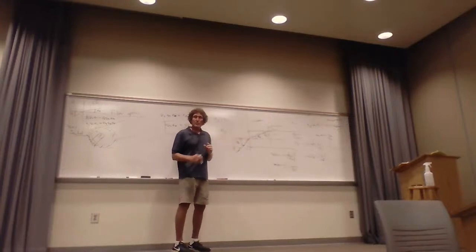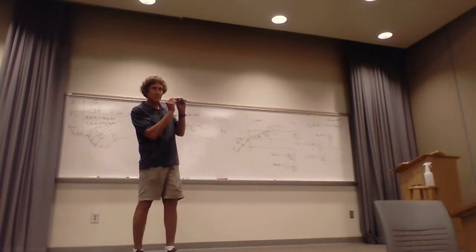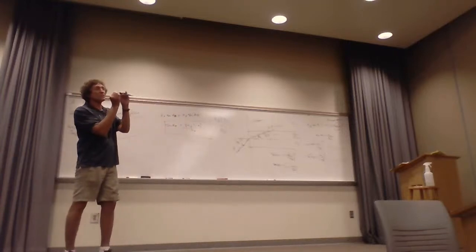But this is important because when you're dealing with fiber optic stuff, alignment becomes a problem. So you got a fiber optic guide here, right? And I'm going to feed it with a laser. Well, if this laser is not aligned perfectly, suppose the critical angle theta A is like 1 degree, then you're not going to get any kind of communication.